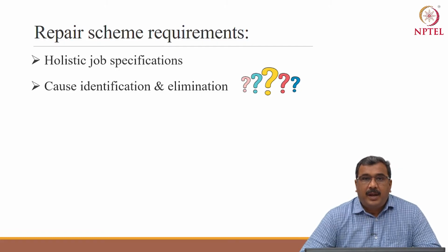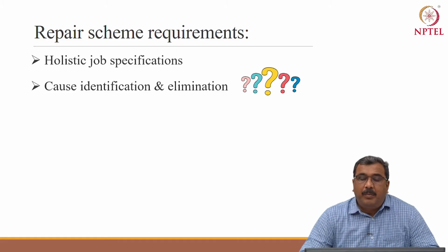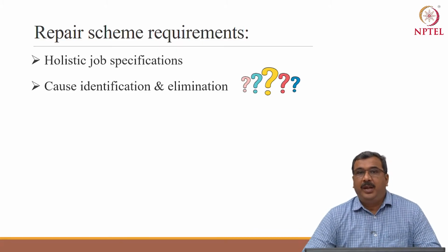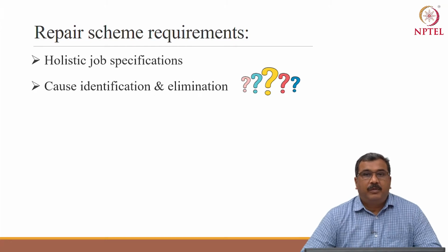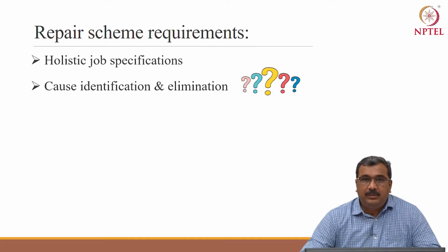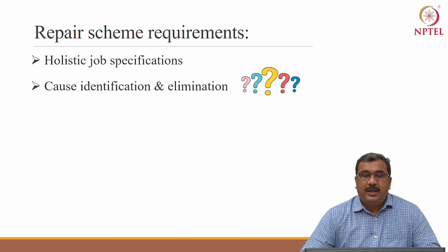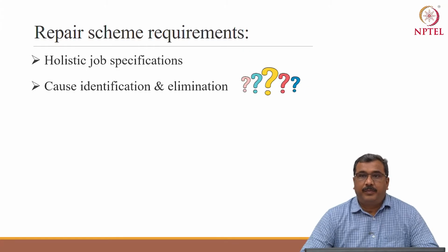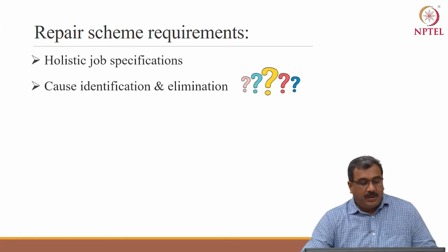If you see a crack, you can repair it with injection grouting, or by making it a V-groove and filling it with some epoxy putty or mortar. Find out why that crack has occurred and prepare a scheme which will eliminate the cause of that crack. So this is the second important point.